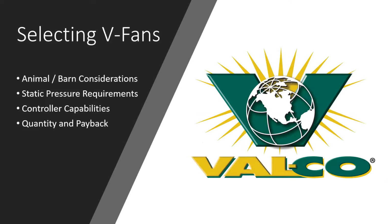Barn considerations, animal set points, temperature set points have huge implications, as we'll see when we get into the simulation. Just a little bit of adjustment in where you're maintaining those temperatures will dictate what stage of ventilation you're in at different times throughout the year, which has a big impact on your payback. So it is something to consider when we're selecting fans and the quantities.